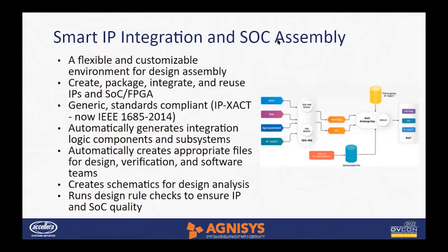So first, we've already seen the creation of the specification and generating various outputs from a single specification, such as RTL, UVM, C header, and HTML. Now here you can see all those specifications are fed into IDS-NG, and RTL output like SystemVerilog and Verilog are created. Now these outputs can further be given as input to SoC Enterprise.